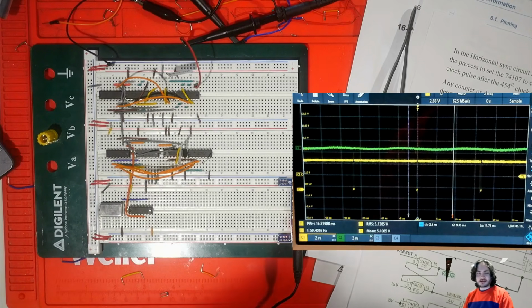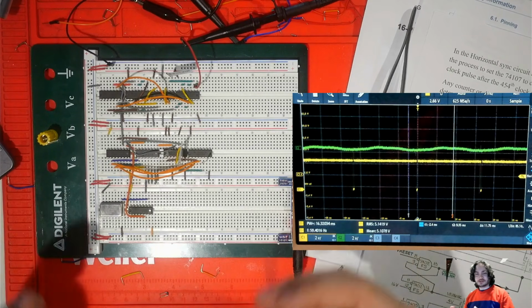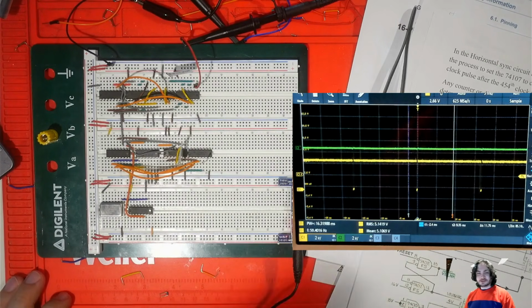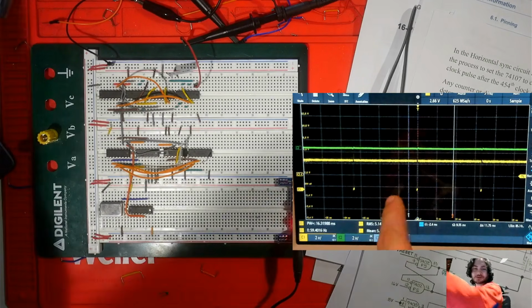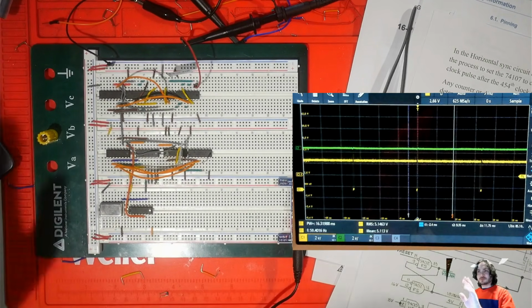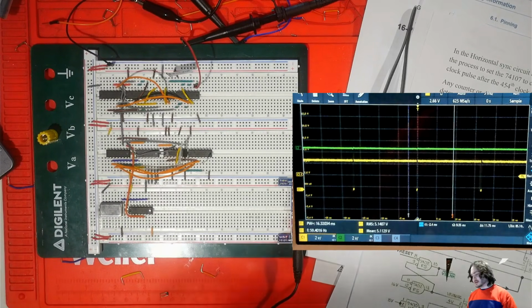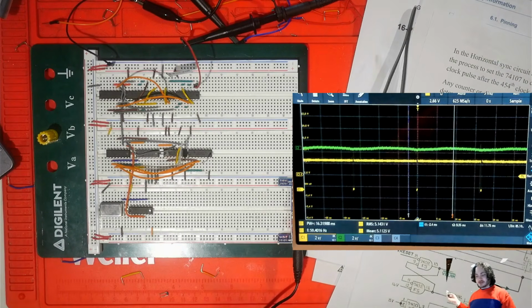Okay, I'm back. I haven't changed anything on here except for my shirt. I've poked in these wires, and I think the reason I was getting some alternate readings of different kilohertz on the scope here was because something was loose. We are now seeing the expected almost 60 hertz. This is actually our vertical syncing signal.